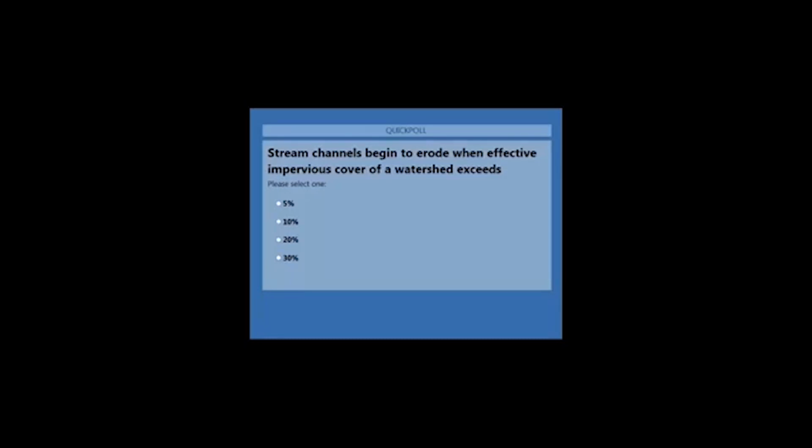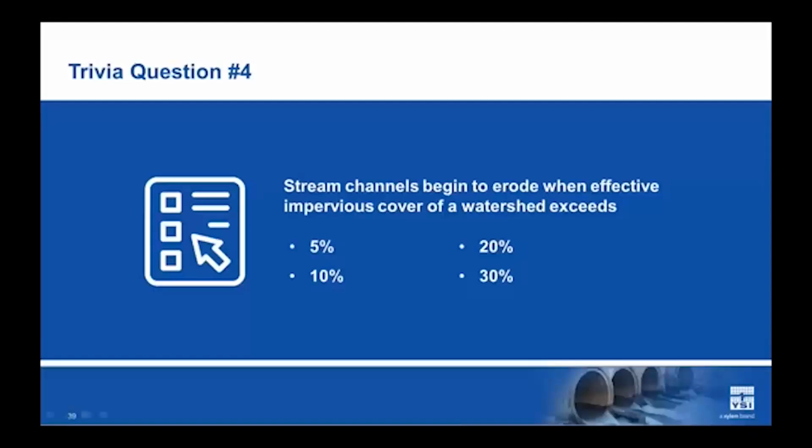A question came in from Chris, really good question here. Are YSI sondes compatible with most SCADA programs? Really important question for stormwater monitoring. The answer is yes, but the reality is that it's not plug and play. You'll have to use a signal output adapter that allows the sonde data to be delivered into the SCADA program.